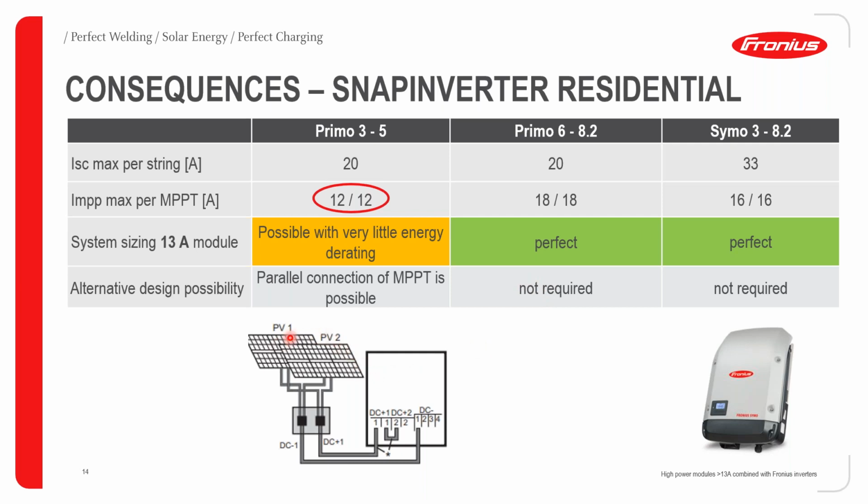As we can see in this figure below, this is how you would connect the 2 MPPTs of the Primo in parallel. So it's just a question of placing a jumper from the second string connection of MPPT1 to the first string connection of MPPT2, and therefore that makes them share the power that is coming from the DC combiner box that you have.